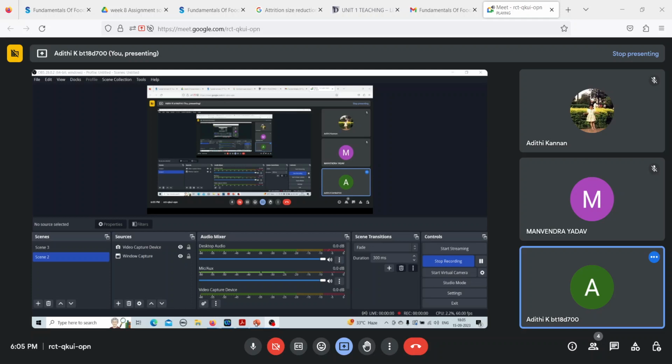So let us look at the table again. You had the sieve number given and you had weight retained given in the question. How you do this is that you assign a stage for each of these sieves. So always your pan will be stage 0, and from the bottom you have to go to the top. So this will be stage 1, this will be stage 2, this will be stage 3, and this will be stage 4. So always start from pan as 0 and work your way upwards as 1, 2, 3 and 4. This is how you assign your stage to each of your sieves.